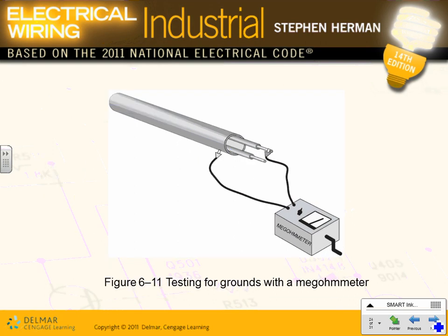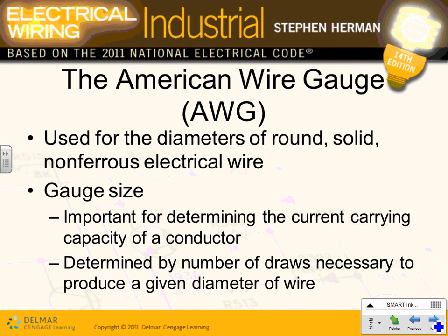The same thing, then you take every phase and the conduit, metallic conduit, of course. Same thing: sending current right here and measuring it back. If the conductor and the conduit are touching each other here, low impedance, low resistance, it indicates that you have a ground fault in the system. That's how you measure the equipment if you're a project manager.